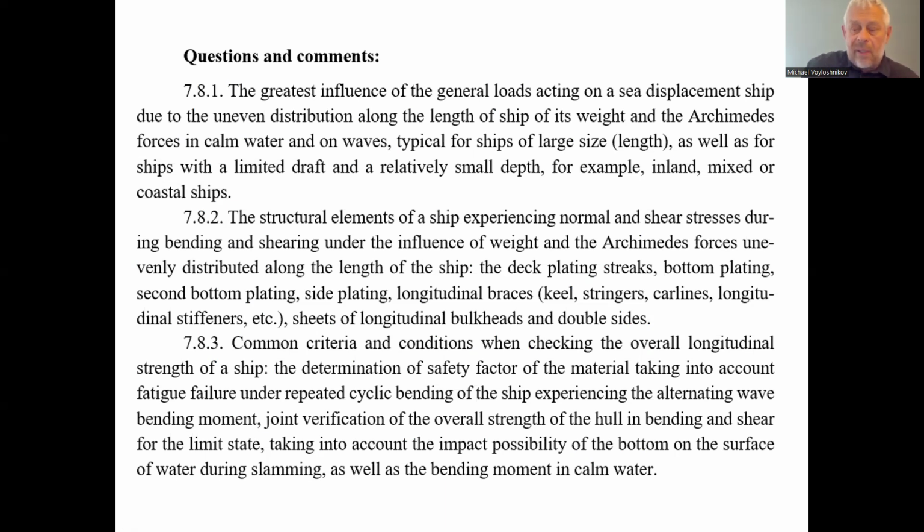If we consider the ship hull strength, there could be other concepts. We consider the concept of general strength. It could be as well local strength. For small ships, the most important could be the concept of local strength, as the general bending moment and the general shearing force are not so important for ships of small lengths.